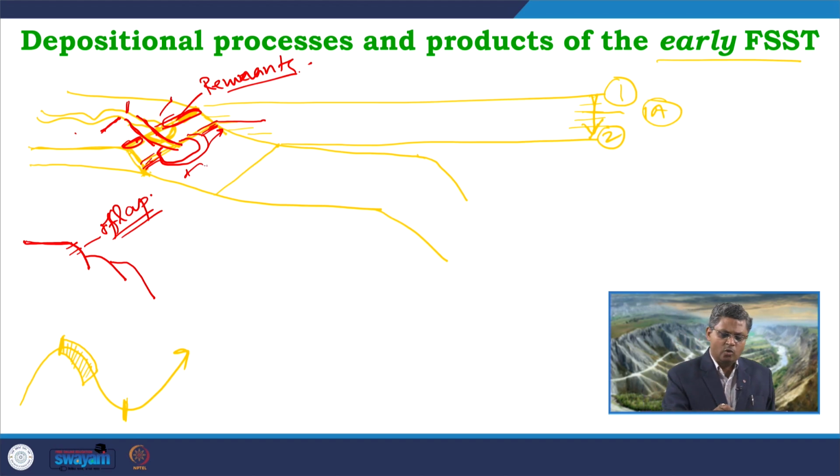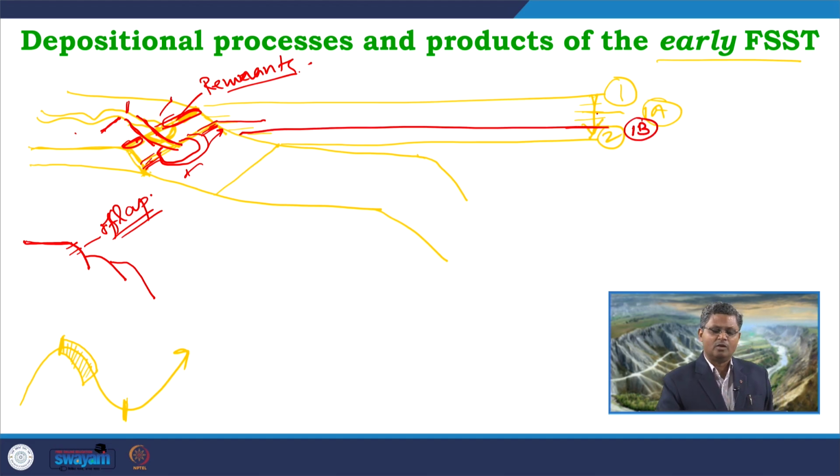Now, in this way, when for example it is coming down to this level, say this is level 1B. For this particular level, the river will further cut down up to this, and the delta will now form over here, and in response to this delta, the wave activities and the longshore currents, the sediments will be distributed along this zone.